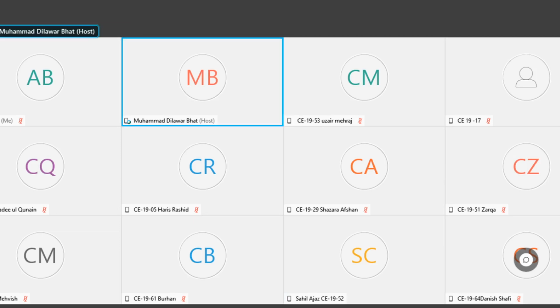No, that will be different in both the cases, because it was a rectangle. In the flange, your b is the width, that comes out to be 150, and d is the depth, that is 50. Whereas in the web portion your b is the width, that is 50, and your depth is how much? Depth is 150. It depends upon the orientation or the dimensions of the rectangle.